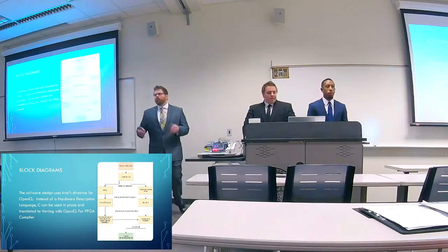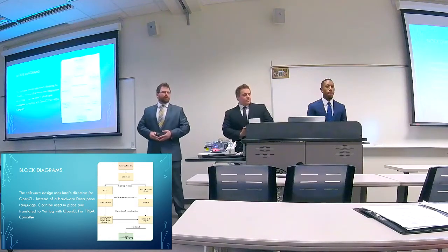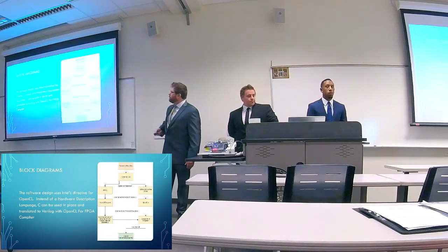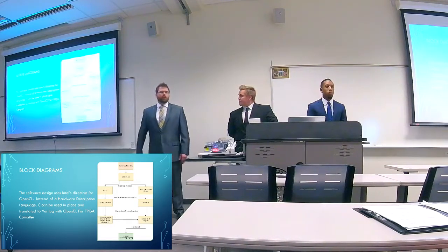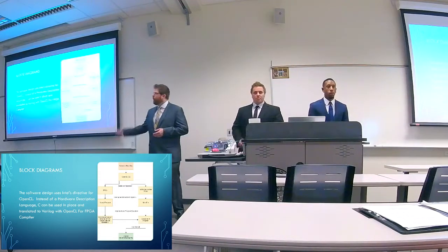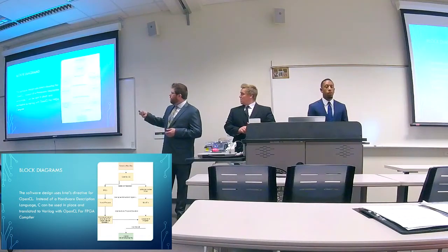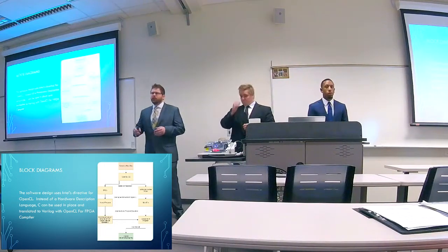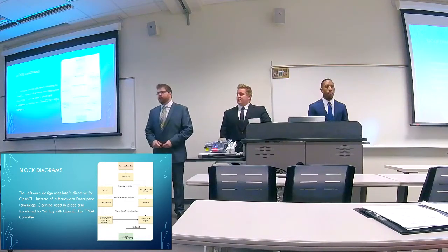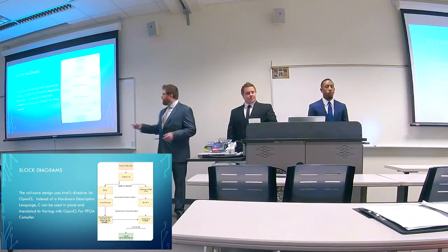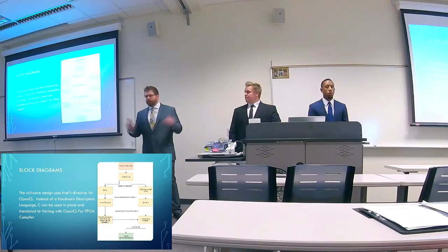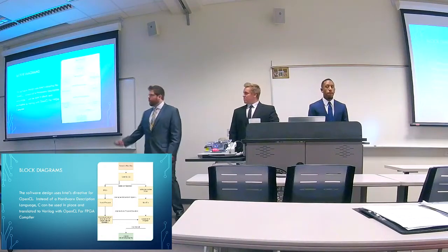Thank you. So when you get the information from the pyrosequencing machine, that's basically considered raw data, and that's what we're starting with here, the genome raw data. And then what we need to do is process this. So we're going to write code in OpenCL, and that will compile into Verilog, and then it will run in a main file and a kernel file. So basically the kernel file does the heavy lifting of doing the operations, and then the main file does the data management. So once it's done, it gives us a result, which will be the placement along the target DNA that those fragments should be assigned.